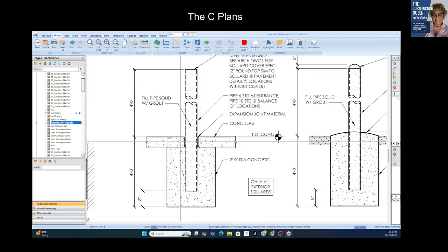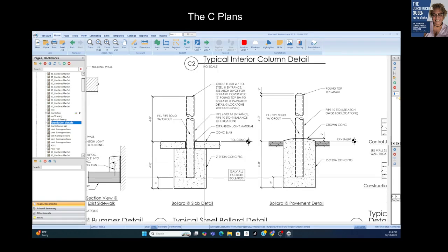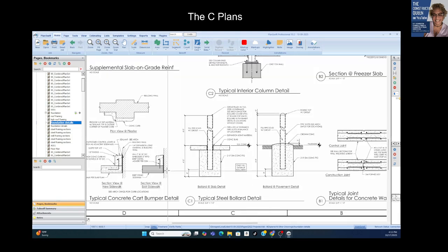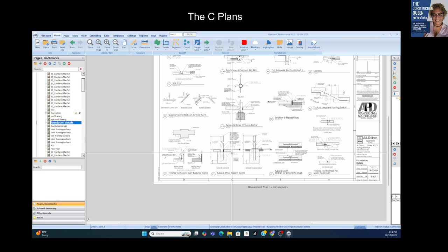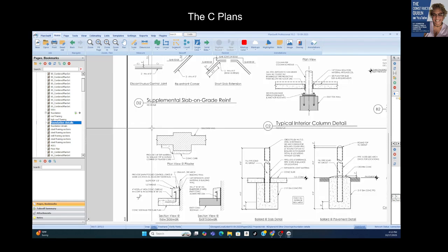Okay, foundation, how our pipes have to sit in, and you have to be able to do all those, determining how many cubic yards. So just make sure you have three dimensions: the width, the height, and the length. And that's divided by 27, and you have cubic yards. All right, so that's going to end this presentation of the structural set.